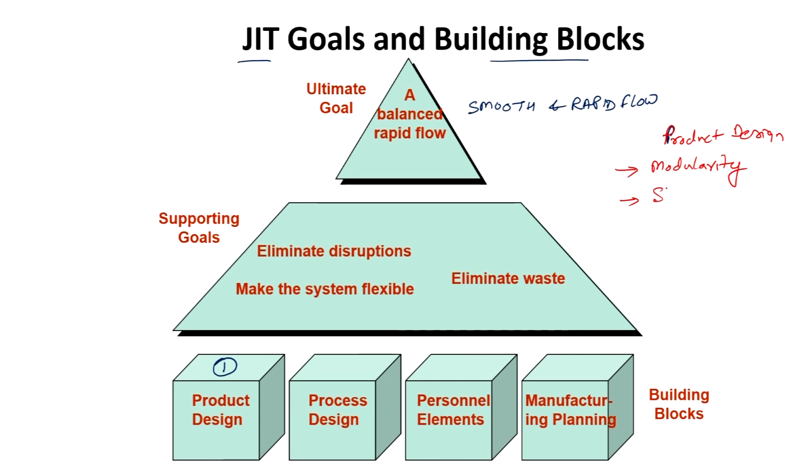Then there should be standardization. If I am able to standardize the parts and components, that will also help in variety reduction and reduce the requirement of inventory. The advantage of modularity is that I can create variety without keeping the inventory of finished goods. So, that is important as far as product design is concerned.